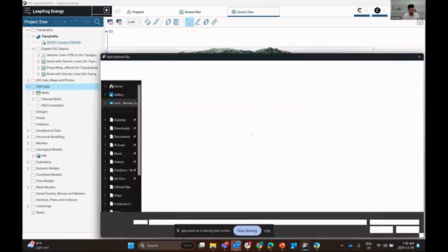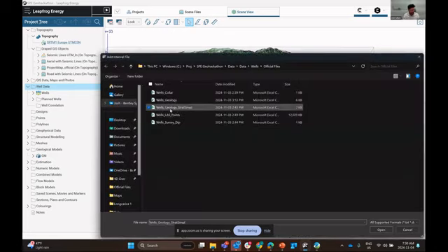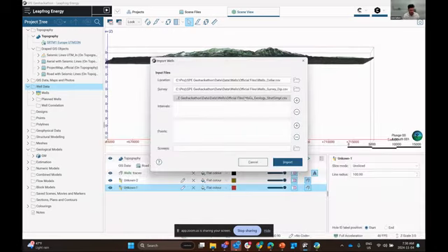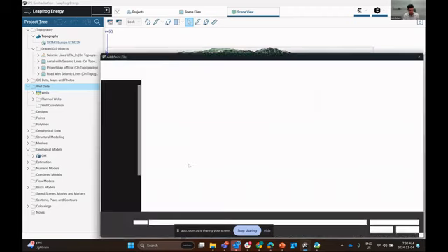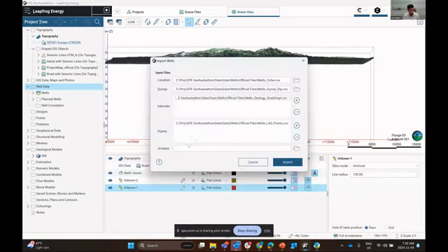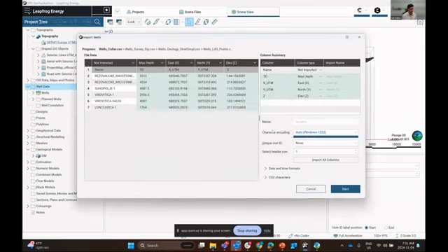For intervals, we're going to import the wells geology strat simplified. This just has additional information from the original geology file that we were just looking at. And we'll also import points. So we'll import these last points. So we've got our location, survey, intervals, and points. These objects are all relational databases. They will have a column that shows a hole ID, which allows you to relate all of these different objects together. So when we press import, it's going to be step 1 of this import dialog.